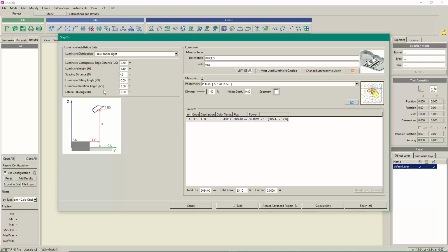And in case, we may also dim the lighting. So if we want to keep the same interdistance, we may reduce the flux emitted by the luminaire using the dimmer, because we may say that we have a sort of dimming with the LED luminaires by managing the currents, the driving currents.